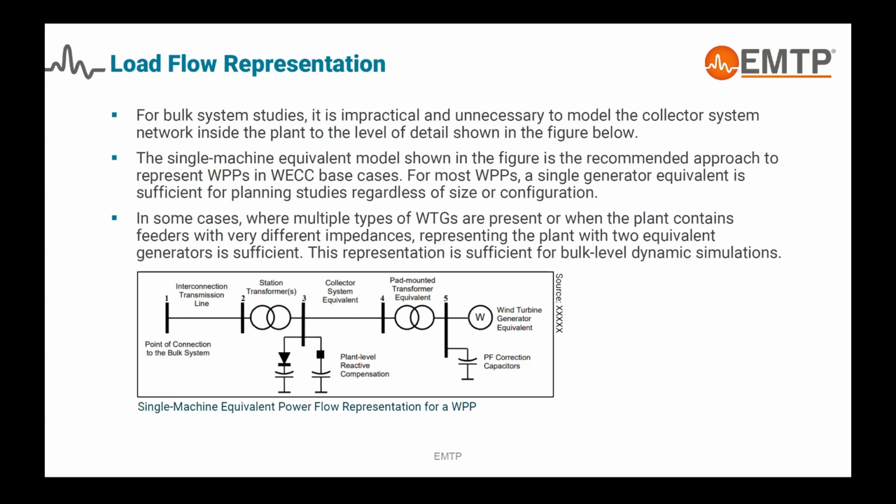This is not bad if you check some standards, documents from WECC, or even papers and books: when you are representing your renewable power plant for transmission planning studies, you can represent it as a single machine. What I want to highlight is that even with this different way to represent the same system, we will see that we are able to get the same results.